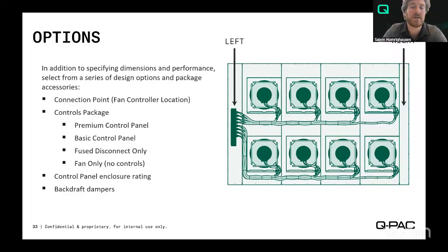All the ECM plug fans are between 40 and 140 pounds, so they should be easily replaceable by no more than 2 people. And you also shouldn't ever need a chain fall either. But again, it takes maybe 10 minutes to swap out one of these in the worst case, and that's from noticing the fan failure to actually completing the swap and turning the unit back on. We used to have actual fan swap races at Q-PAC where we would see how long it took to actually replace one of these ECM plug fans. I think the record is still like under 2 minutes. So it's a very maintainable item.